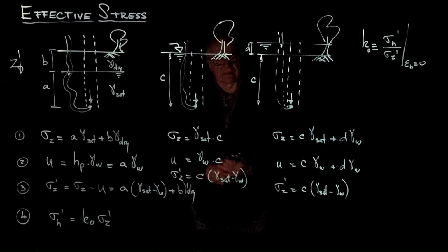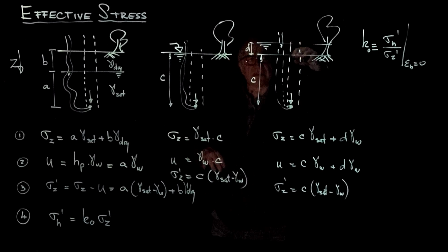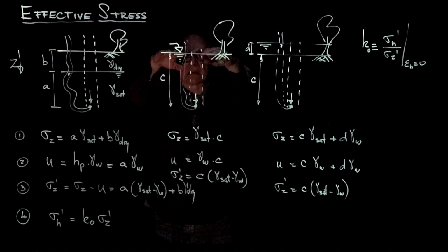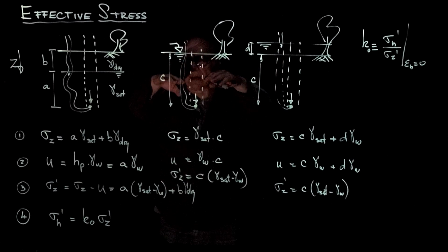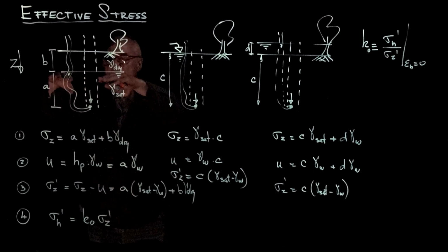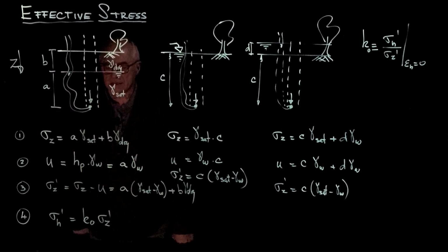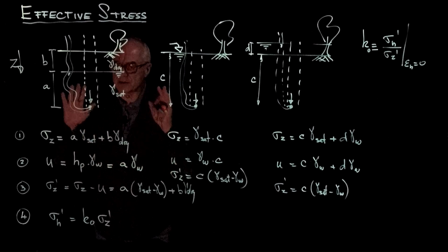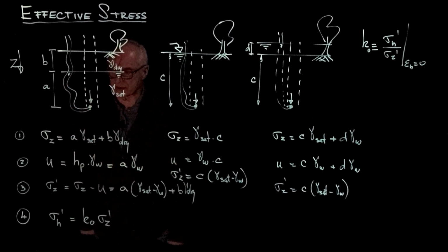Notice that once the flooding recedes, the water table comes down, it reaches the surface with no change in effective stress, but when the water table keeps going down, now the effective stress begins to increase, and there will be settlements if this is the first time that the soil is experiencing this drying condition. This will be exacerbated by capillary effects, but just by pure Terzaghi's effective stress, this will occur as well.